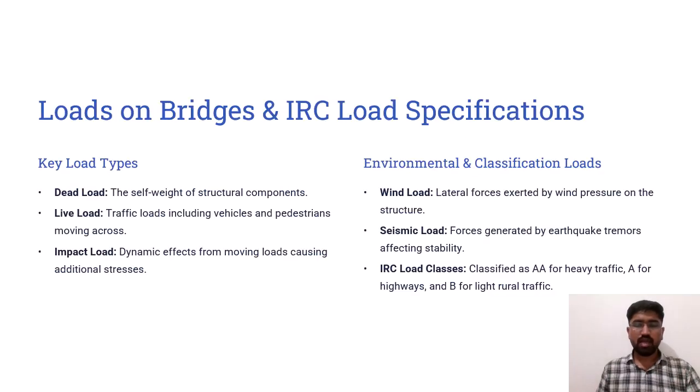Loads on bridges and their IRC load specifications. Key load types: dead load, live load, and impact load. Dead load is the self-load of the structural components. Then live load is the traffic load. Impact load is the dynamic effect from moving loads causing additional stresses.